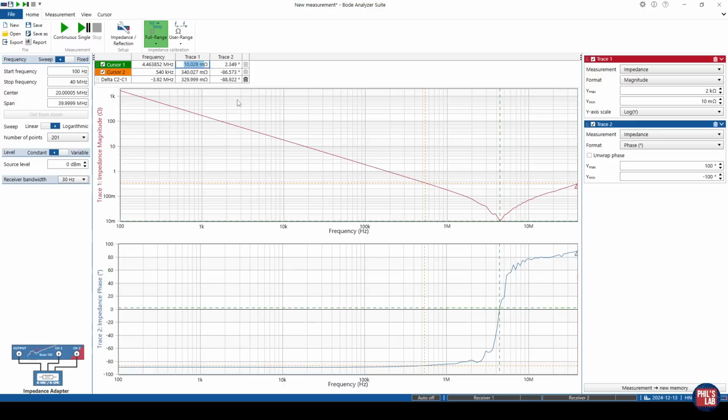Remember, our impedance measurement technique, this one is only optimum around 20 milliohms, so there could be some error in this measurement, of course. There might be also contact resistance in this region, but for now we can estimate we have about 10 milliohms at self-resonance of ESR, and the self-resonance happens at about 4.5 megahertz.